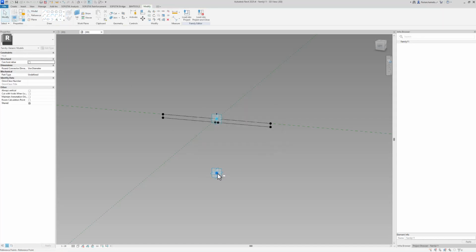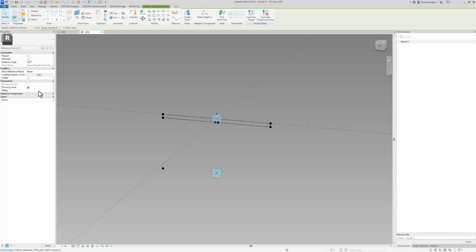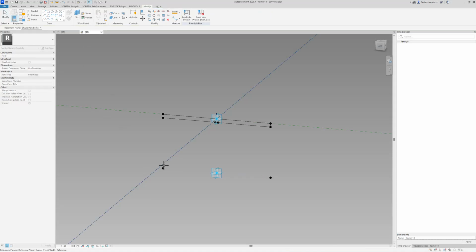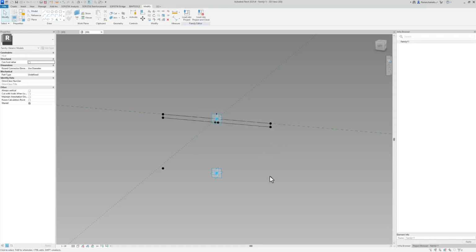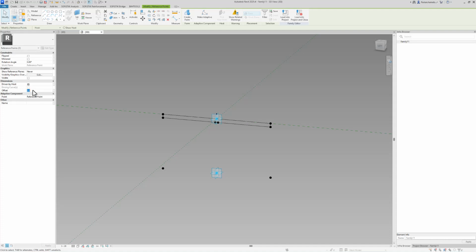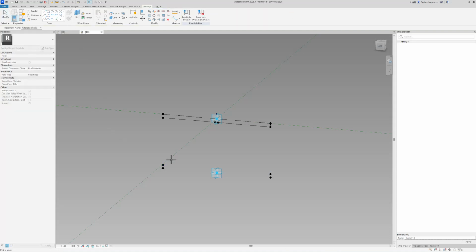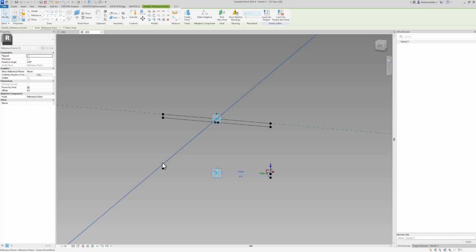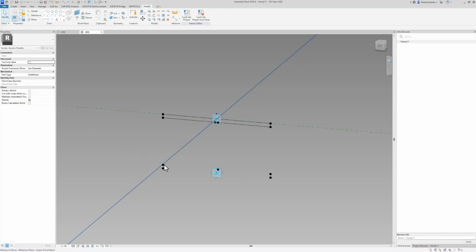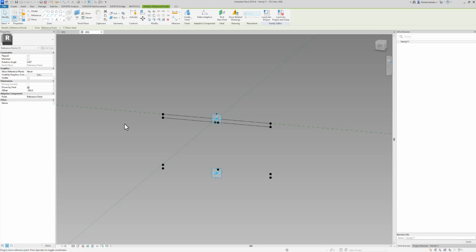with 400 offset as well as -400 offset, a thickness of 28 for the 2 points in vertical direction. Can select both of them by holding Control and simply assigning 28 to them. And then horizontal displacement for these 2 points to represent the thickness of the web. I select it, assign 390 to it, as well as -390.